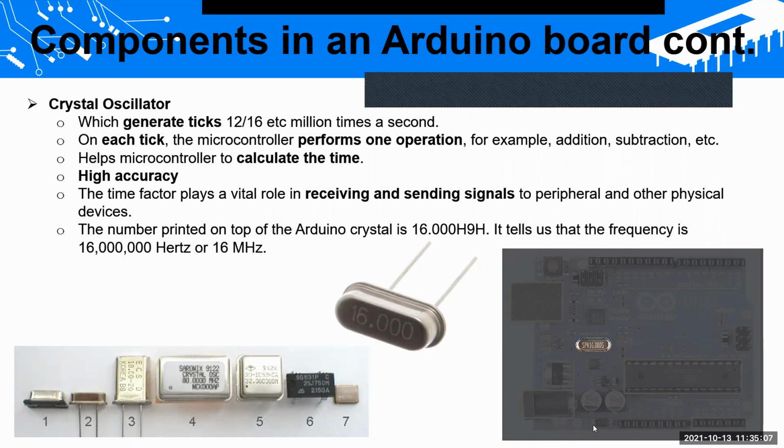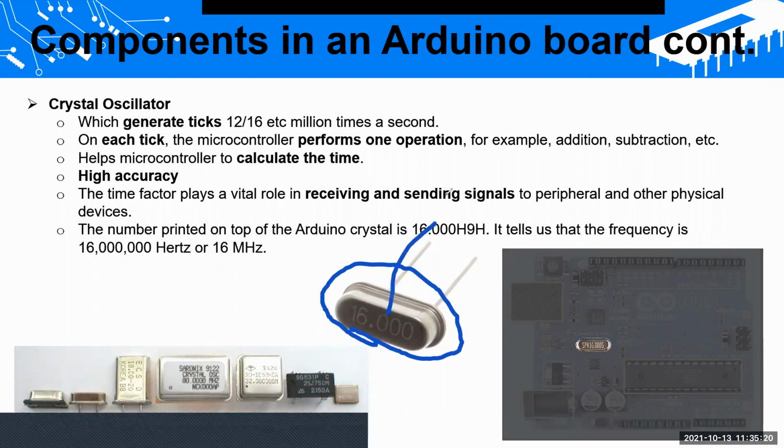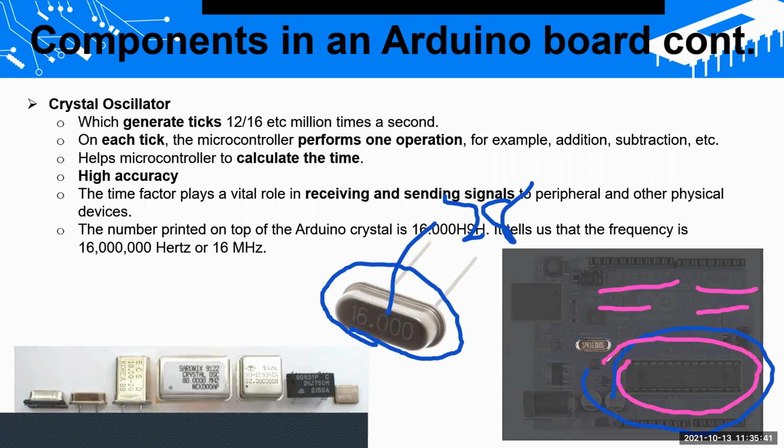Someone can ask whether we can increase the timing. All the timing is done by the crystal oscillator, no? So someone can ask whether, if we increase this 16 to something like 28 megahertz, it increases the clock of the microcontroller. Nobody asked, so I'm going to tell the answer. The thing is, you can't, because the other peripherals, the bus speeds and the working conditions of the microcontroller are fixed.